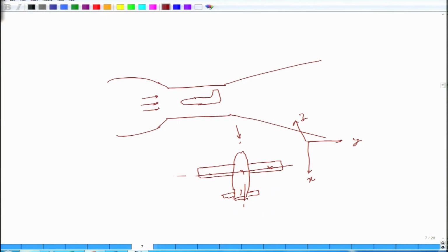That will ensure that if the flow is unidirectional as well as uniform approaching the aircraft model, then at equidistant points these properties are essentially the same. That is, there is no variation of the flow properties as well as thermodynamic properties along the y as well as the z direction, and we are interested in seeing the changes only along the x axis. Then we say that we have brought down a three dimensional flow to one dimensional.